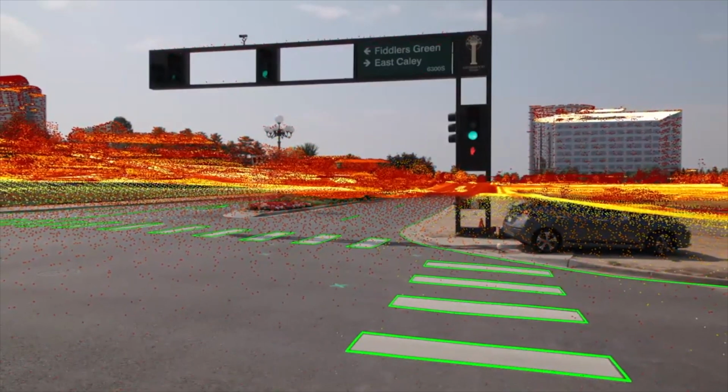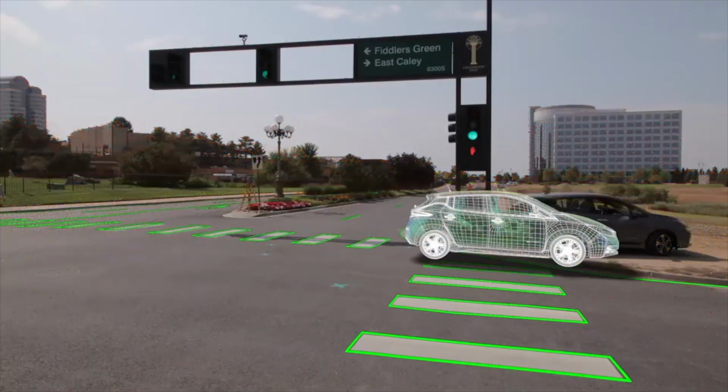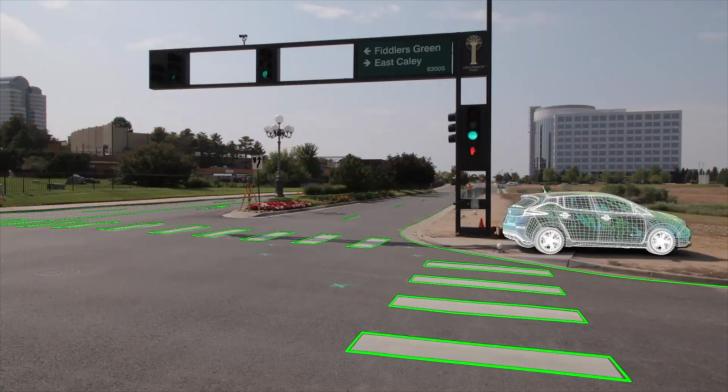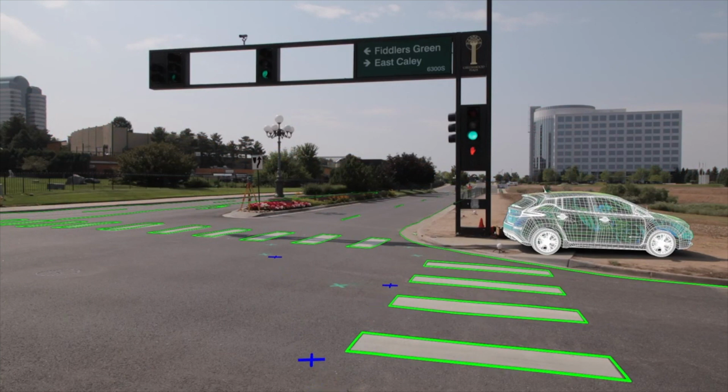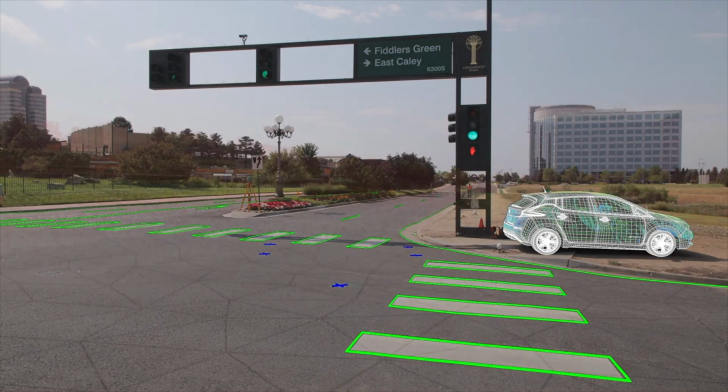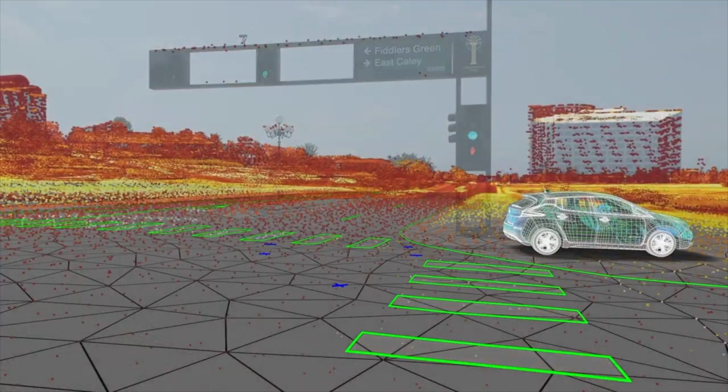MLS, together with photogrammetry, is used to provide a higher quality and faster response. It provides the computer of vehicles with the information about the surrounding environment. As distance data is recorded with laser scanners, it could help to maintain a suitable speed and automatically follow the previous vehicle. An intelligent driving system also obtains photogrammetry data to analyze extra information such as signage and lines in this case.